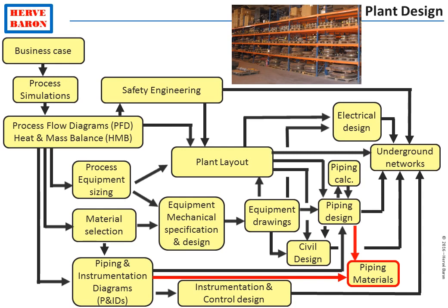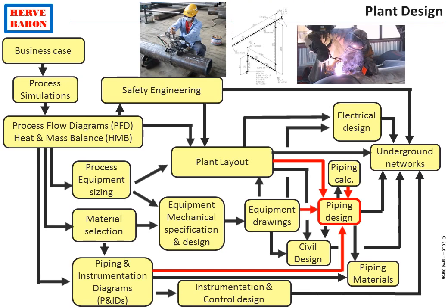Once piping materials are ordered, the other thing that is required at site to progress with piping construction are the drawings. These drawings will require that the connections to equipment are finalized. This will require to have vendor drawings, finalized vendor drawings for equipment as well as inline instrumentation.